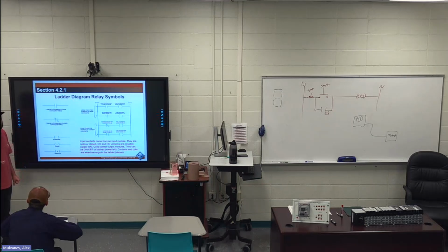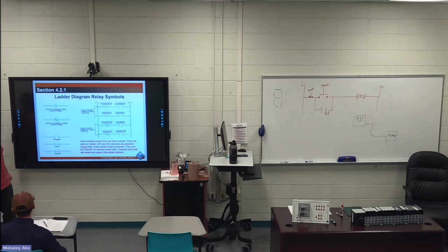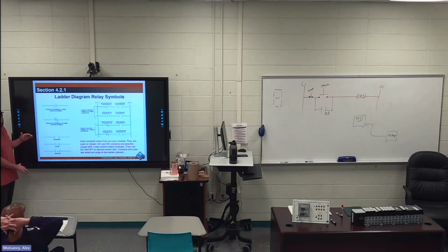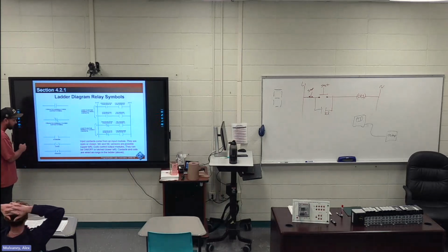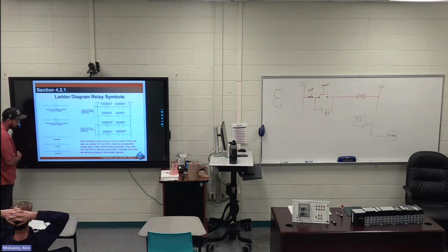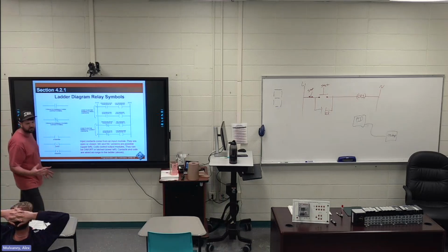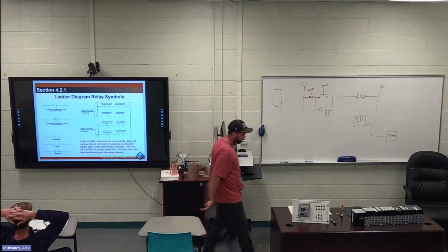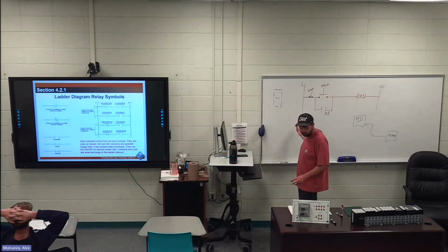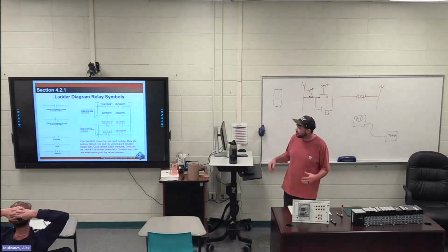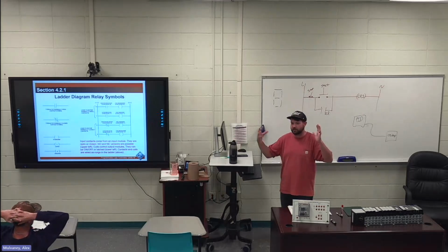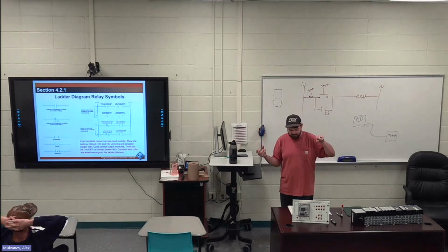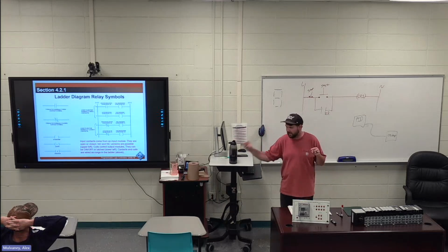And there's different advantages to that, like making sure stuff's not pushed at the same time. It's separating your code out. So it's going to look a little bit different than that. You would just have a start button on the latch, and then you would have the stop button on the unlatch part of that. So it's just a little bit different than how you would draw it on the hardwired circuit. But if you think about it more like my inputs going into a computer, it makes more sense that when I push this button, this is going to latch and turn on.